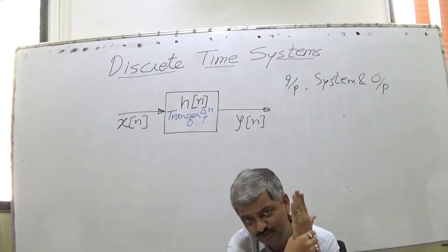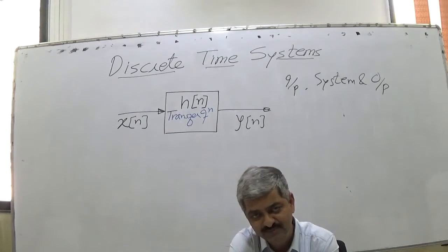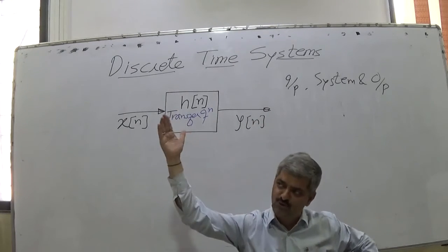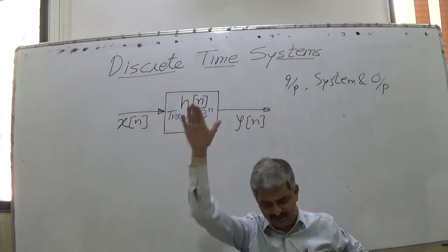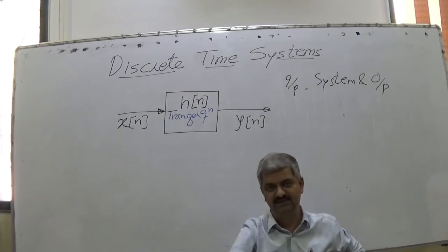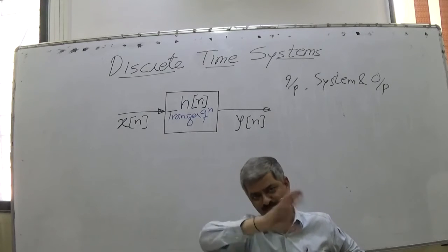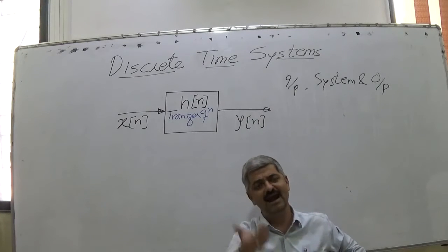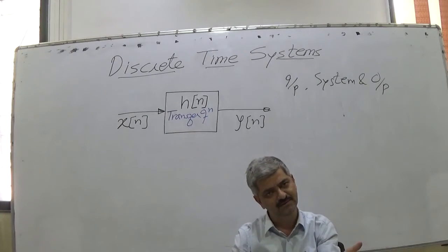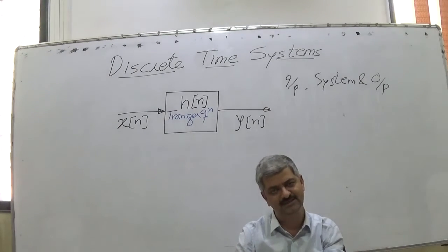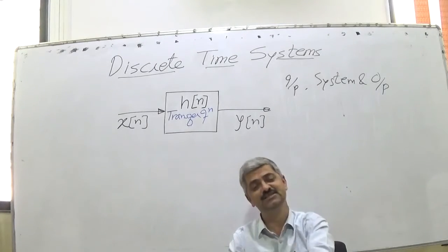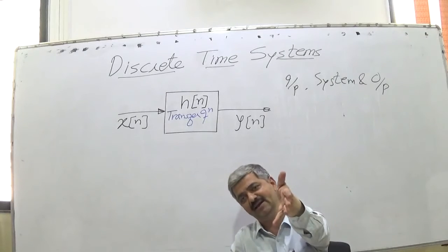Continuously sample the input signal, store it, process it, deliver it. It's real time, meaning the analog to digital converter is continuously dumping digital data into computer memory. You have a computer program which takes this data stream, mixes it in an appropriate manner, and puts it into another memory block, and there is another program which takes up those bytes and puts them on the DAC.